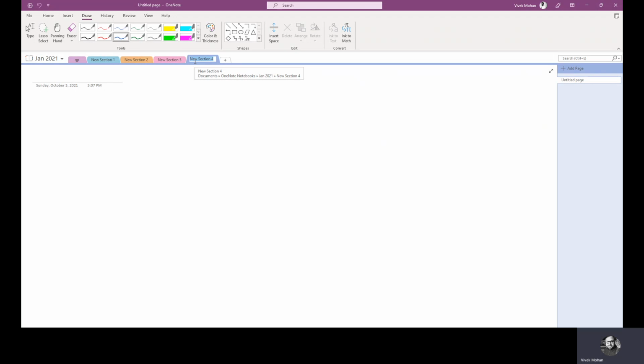Okay, now we will see the relationship between P, Q and S, which you might have already gone through in your basic courses. So the voltmeter indicates E, the ammeter indicates I, the watt meter indicates plus P watts, and my var meter indicates plus Q vars. So knowing that P and Q are positive, we know that the load absorbs both active and reactive power, which is measured by the var meter and the watt meter. Consequently, the line current I lags behind E by an angle theta.